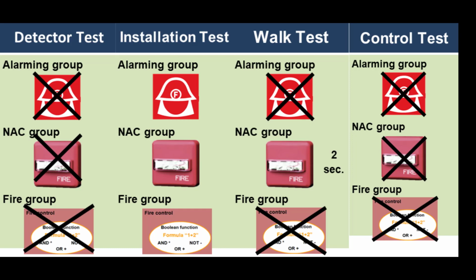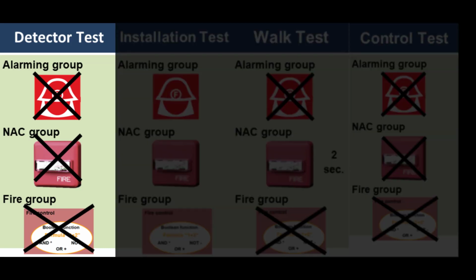Please understand that you can customize some testing parameters that can make the standard test mode behavior change. Also, be sure to take the appropriate precautions when testing critical application systems, such as a panel with fire extinguishing capabilities. First, let's look at the detector test. The detector test is a hardware function test for devices and their allocation to the detection tree. No alarm devices or controls are activated.